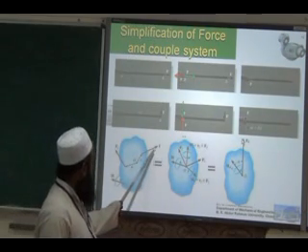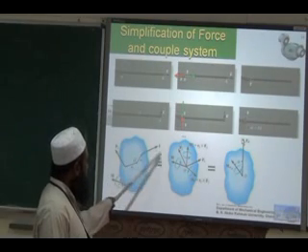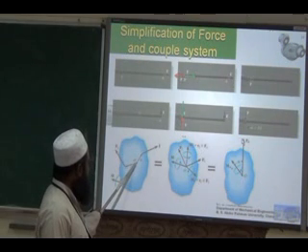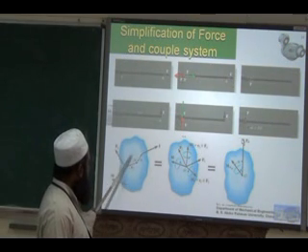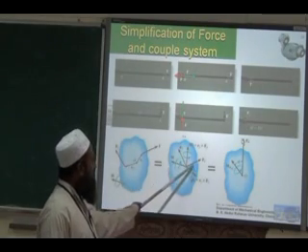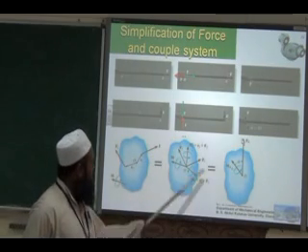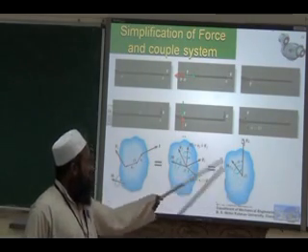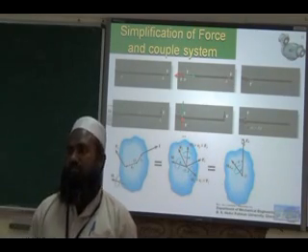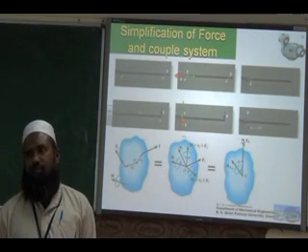Here, these forces are inclined in different directions. So when you transmit to a single point, force F1 from here is getting transmitted to point O. F2 is also transmitted to point O. So when you transmit it, it will introduce a moment also. So we have to find out the resultant for all the transmitted forces, and also the moment developed due to transmission. So this is called a single resultant force and moment system.